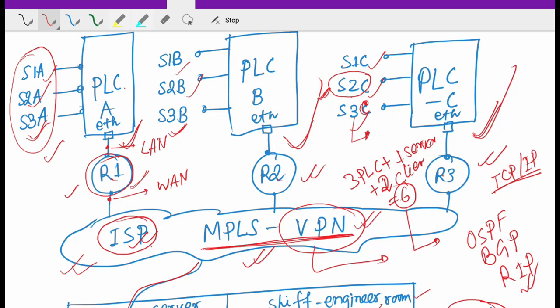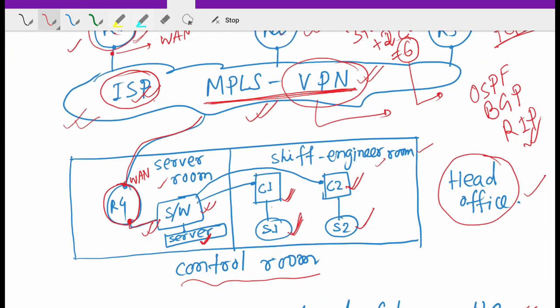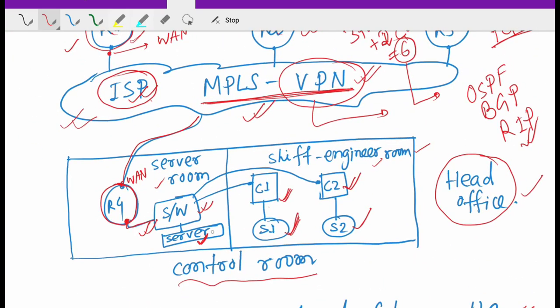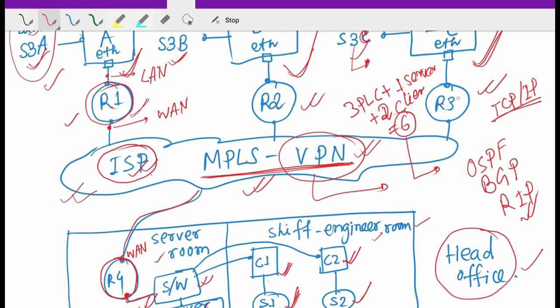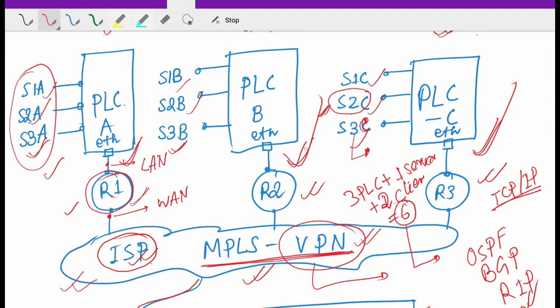Whatever the configuration is, each IP device should be able to get a ping response after sending a request to any other device. For example, if you send a ping request from the server to PLC B, then you should be able to get the ping response from PLC B. So the network connection can be anything. Everything is about getting the ping response.